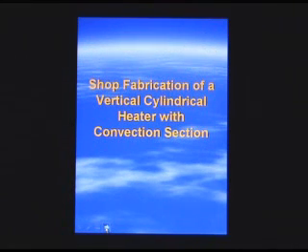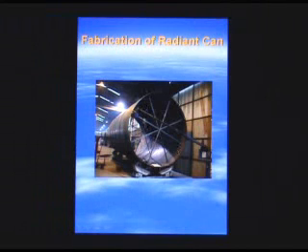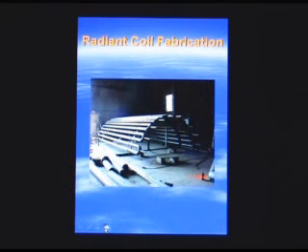This is the fabrication of a fired heater for the drill site 1J for the North Slope application. It shows you the shell cans. This would be the radiant section. Shows how they roll it. These are spiders inside to keep it round. This is the vertical coil that will be inserted inside the radiant section. These pins on the bottom are guides that keep the coil aligned inside the heater. For this unit, the heater was hung from the top inside the radiant section.